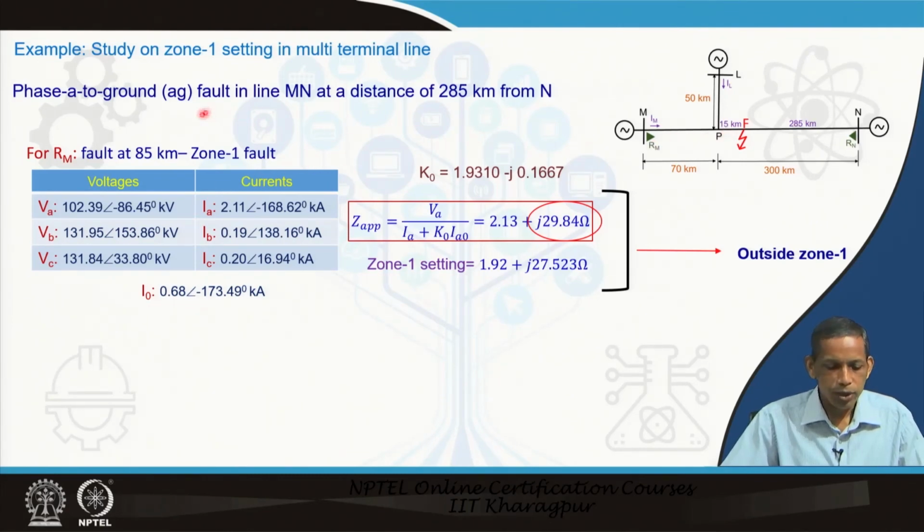By creating the phase A to ground fault, the corresponding phasor voltage and the phasor currents are noted here. So, we see here the corresponding phase A current is much higher than the other phases. Now, there will be infeed from this side during that moment.